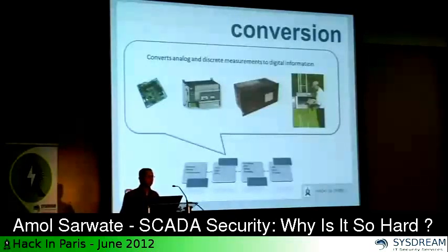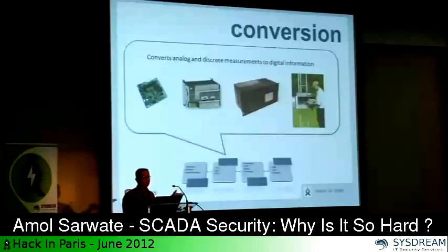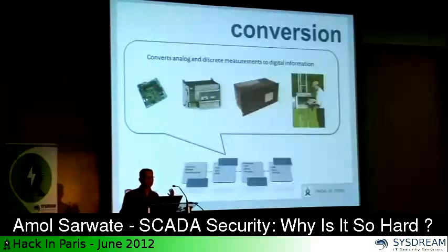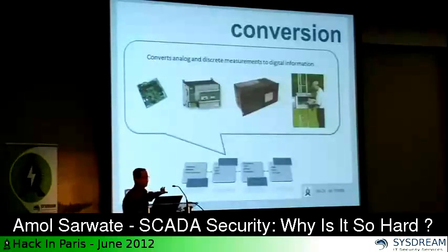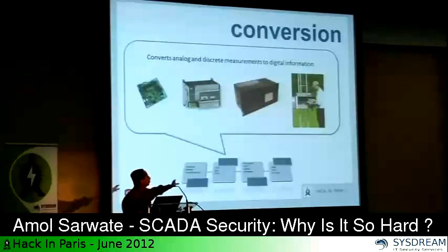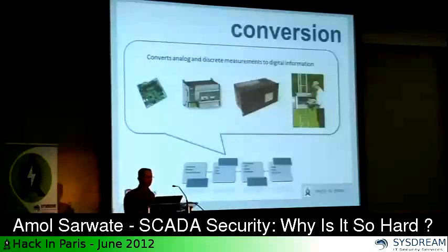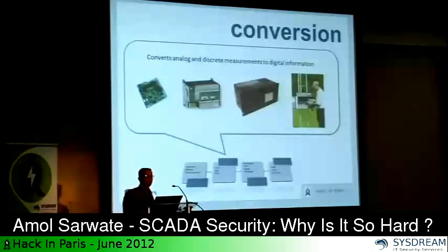And just to give you an example of how big they are, you can see a man there. He's holding a PLC, which is most probably attached to some sort of electric pole or a windmill pole or something like that. They are this size. So in this framework of a SCADA system, number one component, data acquisition, where you acquire data. Two-way communication with data conversion, which converts it to digital form.